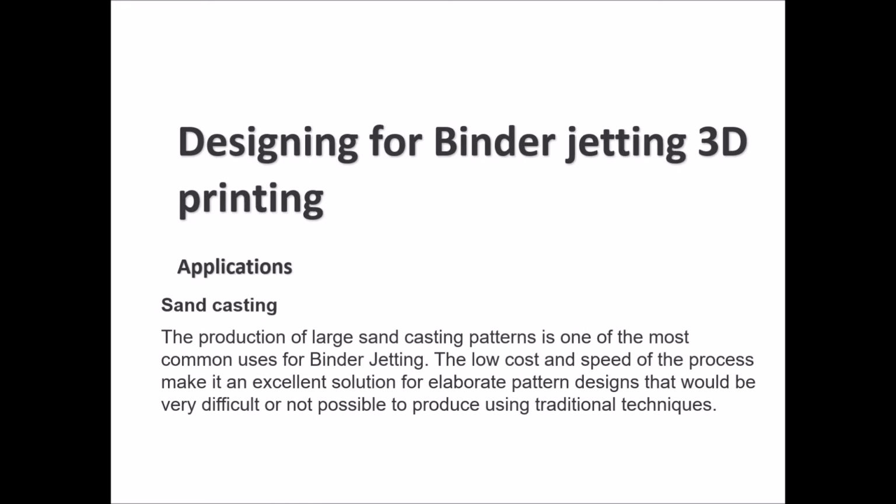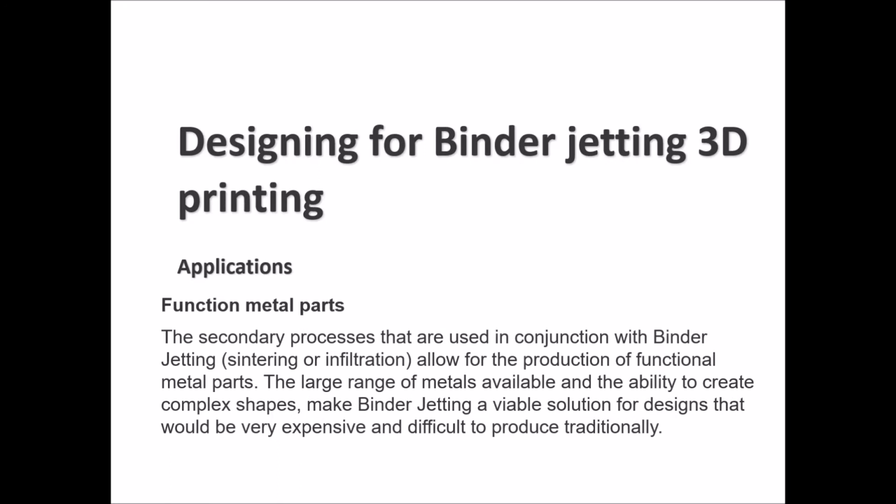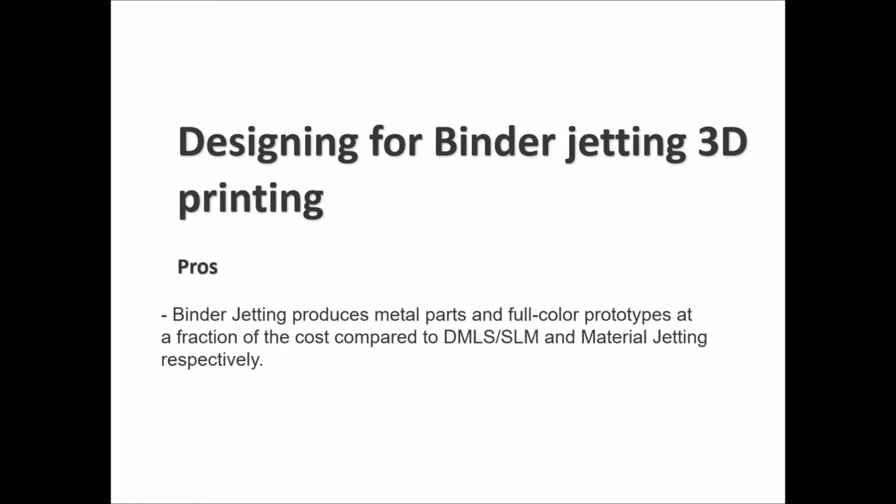For sand casting, that's another application where you can create sand casting patterns and molds, because they can give you a low cost and a high speed delivery for the parts, which can be an excellent solution to create pattern designs that are difficult or not possible to be produced with the traditional techniques. You can also create functional metal parts through this 3D printing process.